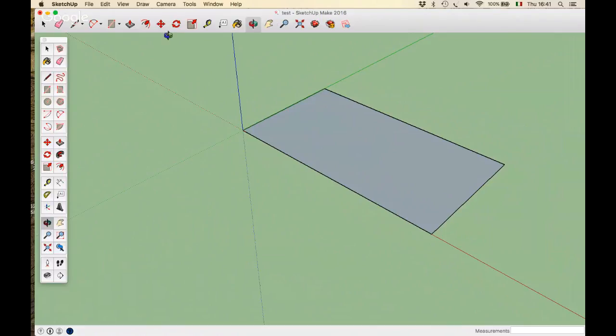So okay, let's go to the next step, and let's select this tool that is called the offset tool, and let's create our walls. So what are we doing here? It's creating a smaller rectangle inside the one that we just did. And again, we can just create a random one and then input the right dimension that we want it to have. And we want this offset to be 0,44. So you just see it adjusted automatically. You type the right dimensions, and then it works.